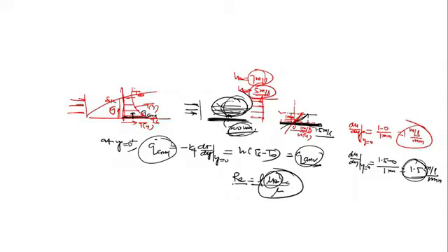Why? Because now, since velocity increases, it will take a smaller thickness to reach 99% of the upstream velocity, yes or no? When we increase the velocity or the Reynolds number, the gradient increases, and to attain the upstream velocity it will require a somewhat shorter distance.